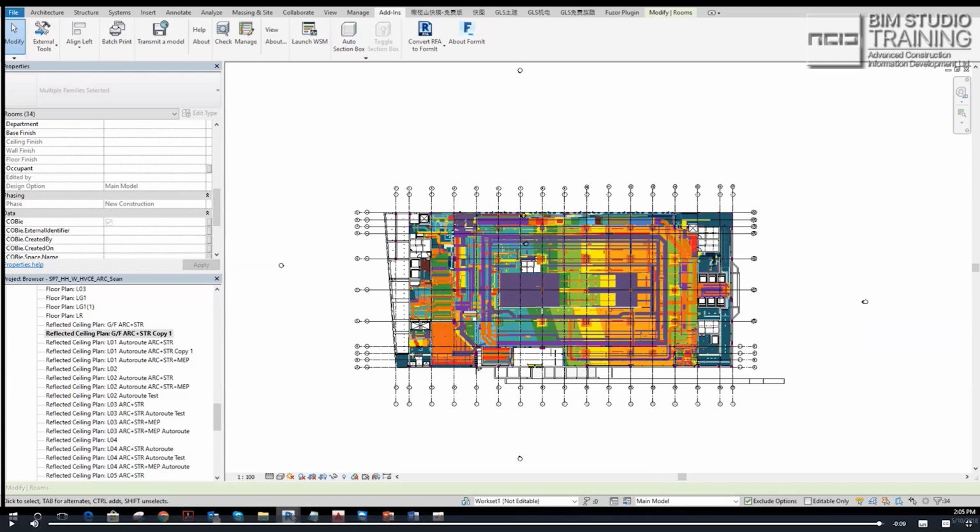In between, we wrote software to detect the space. So what you see looks like a heat map. It is not a heat map, it's a space map. Space map means the space between above ceiling and below beam. So the more red, there's less space. The more blue, more space.